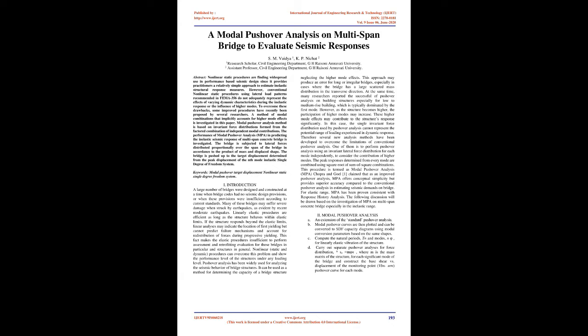It can be used as a method for determining the capacity of a bridge structure, neglecting the higher mode effects. This approach may produce an error for long or irregular bridges, especially in cases where the bridge has a large scattered mass distribution in the transverse direction. At the same time, many researchers reported the success of pushover analysis on building structures, especially for low to medium rise buildings, which are typically dominated by the first mode.